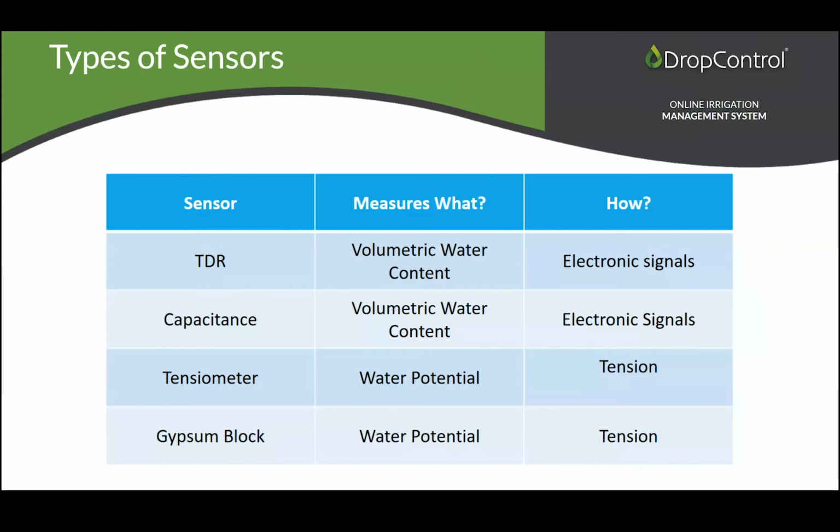There are different types of sensors, and there's usually confusion around this and which sensors to use. So mainly we have 2 families of sensors, the ones that measure volumetric water content. Those are usually the capacitance probes known in the market, and then water potential or tensiometers. So one's monitoring the amount of water in the soil, the other one's monitoring vacuum pressure in the soil. So it's 2 different technologies, 2 different methods to get to the same result, but they are used differently.